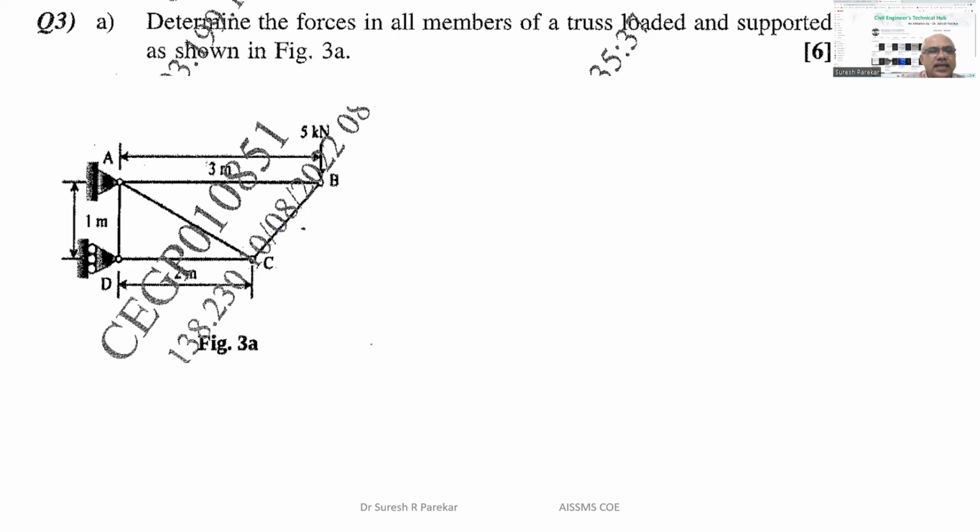Now in this, if we will see, we have this will be reaction and this will be member. So this vertical cannot be balanced by anything, so we can make it as 0. So okay, now I will draw the diagram, and then we will find forces in the members. So we have this member, but with force 0. Then we have two reactions over here.